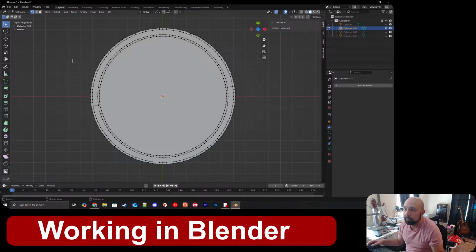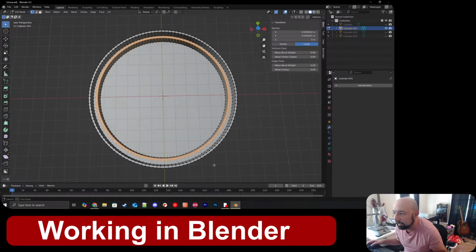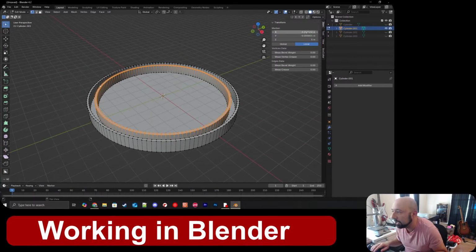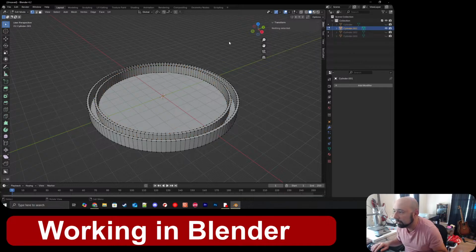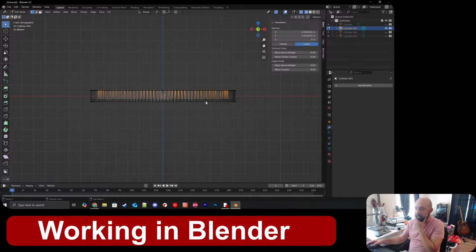What is it, Shift or Alt? Alt will get that whole loop except for that bit. And I also want to get that loop and that loop. Now, that should only be the top vertices, right? If I go to side view, no, reselect, one, side view, X-ray mode. All right, so it only has the top vertices.